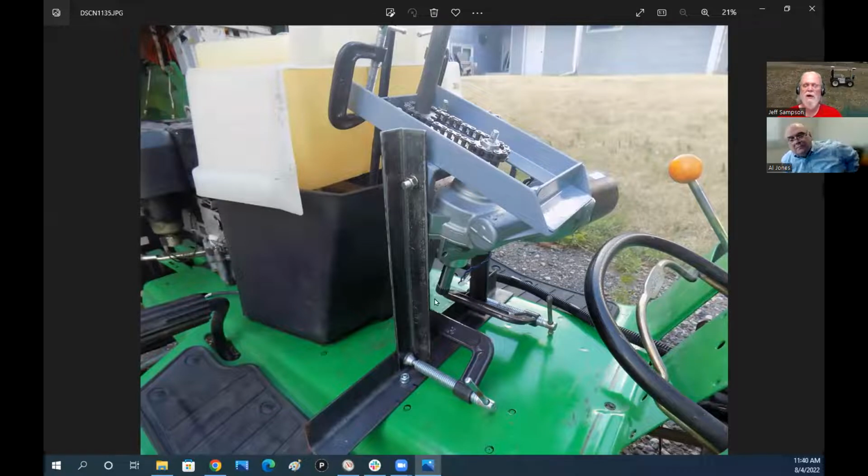But it's got a hole in the bottom, so I could mount a pot down here also. So then I'd have a redundant sensor, one on the top here and one on the bottom down here. So if I get real ambitious, I could have both of those and constantly compare those. And if they're not matching within some percentage, say, oh, something broke or a wire fell off or something shorted out or whatever. So that's something you could add to it to take care of that.